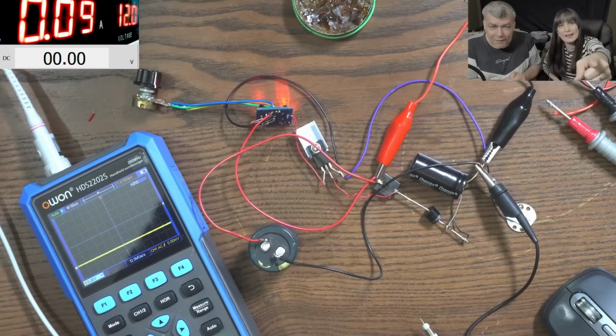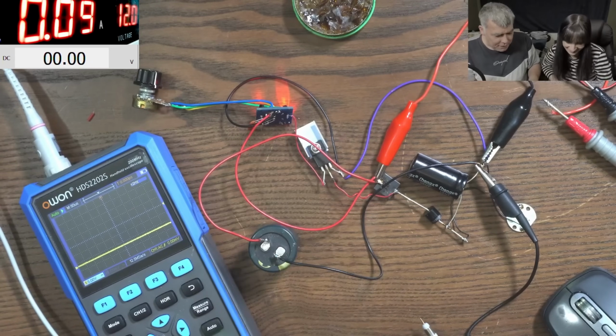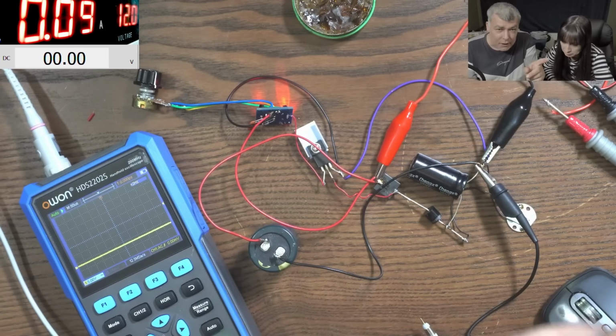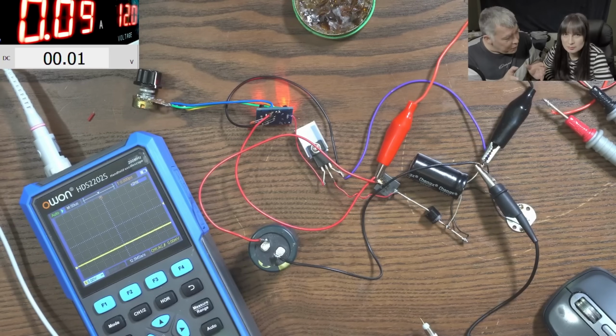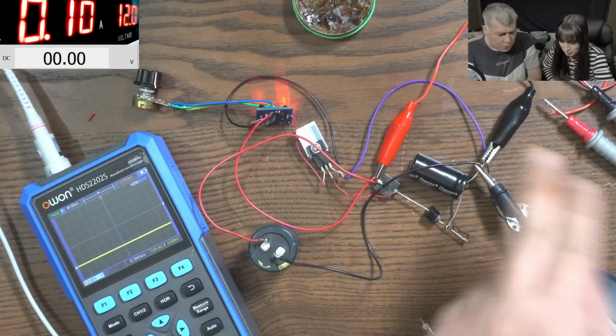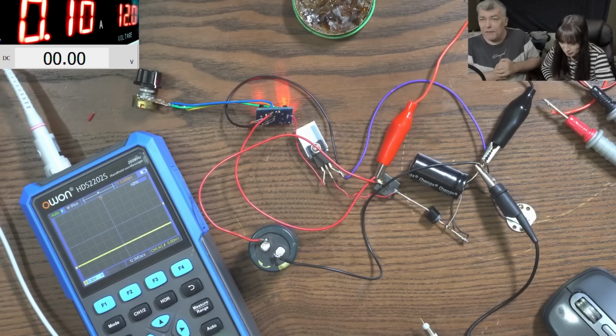But I still got like 100 million. Yeah, but you still modulate this. Just because you can't see it working badly, you can adjust the current, and it's working how it's supposed to, that doesn't mean it's right. You have to do it right. You have to get rid of any interference from the switching power supply. You don't want the switching to go onto your power lines. So connect straight to the capacitor again.